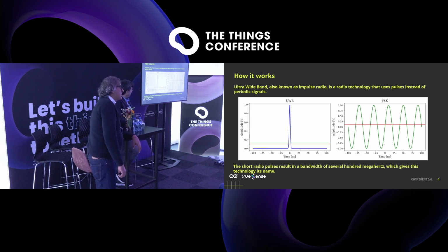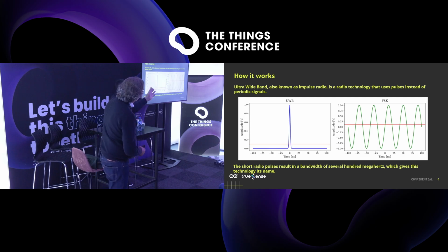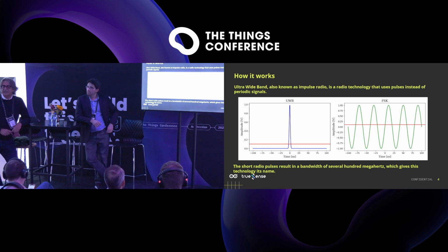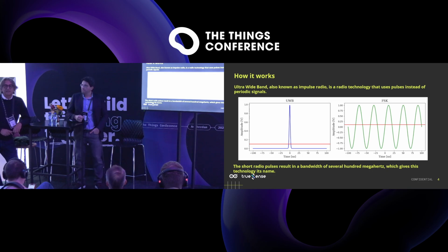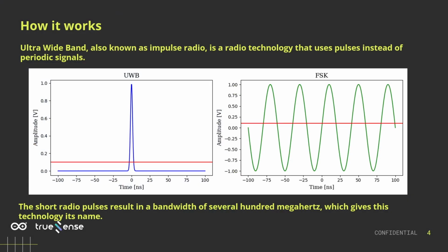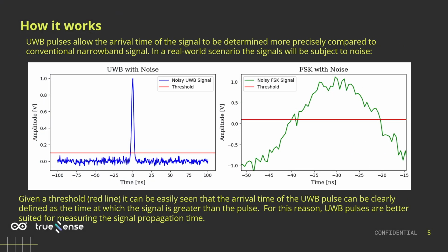Why so? Because the way the radio frequency is managed with ultra-wideband is completely different. Other technologies normally use some kind of modulation. Here I'm making an example of FSK modulation, so it's the classic sinusoid. While in ultra-wideband, what you do is you use pulses, like a telegraph, okay? And this gives a couple of advantages. Like in the telegraph, even if you have big noise in the environment, you will still be able to perceive this pulse. And the second thing, which doesn't appear in this slide, but is evident in the next, which is